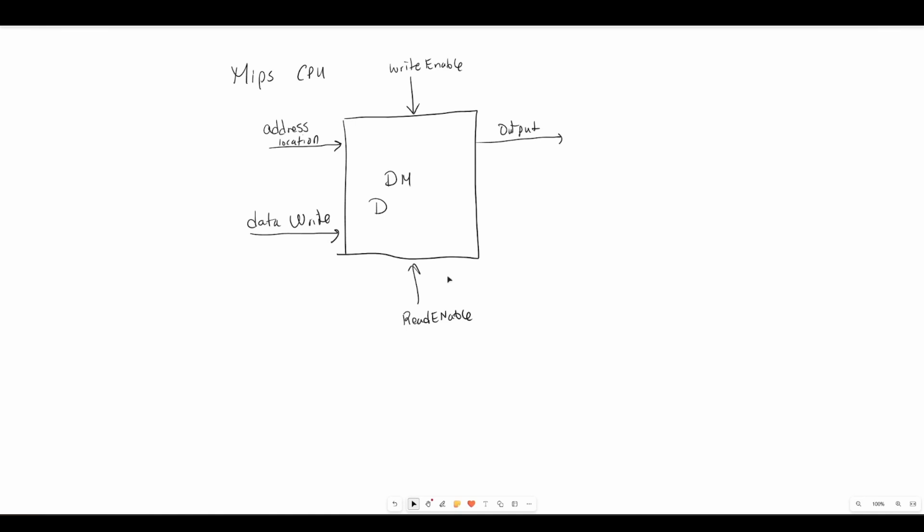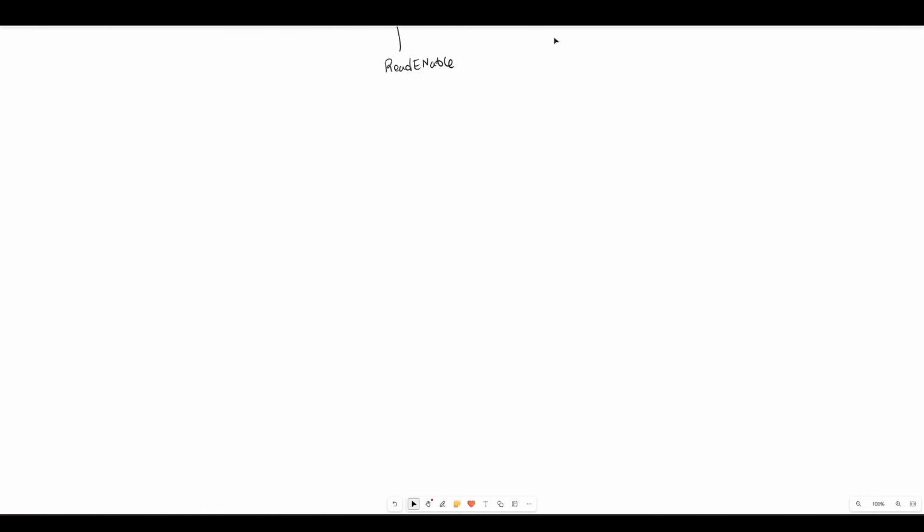So how exactly are we going to build this? Like last time, we use flip-flops. Let's see if we can do one real quick. I have one flip-flop, two flip-flops, three, four, and then we have a D and a Q, a D and a Q, a D and a Q. We also need a clock because we have to clock the flip-flops, and we also need the enable signal.